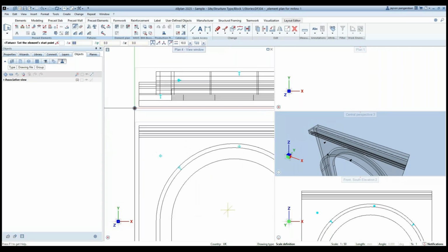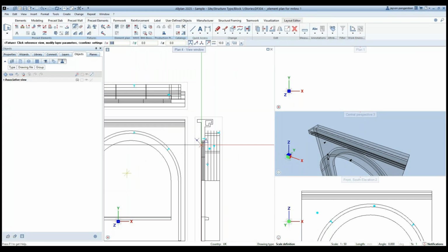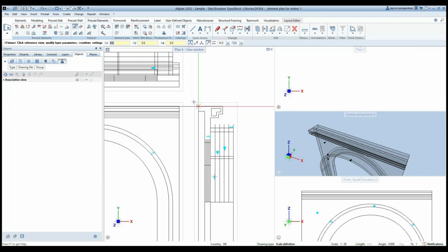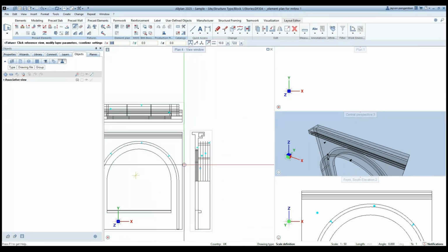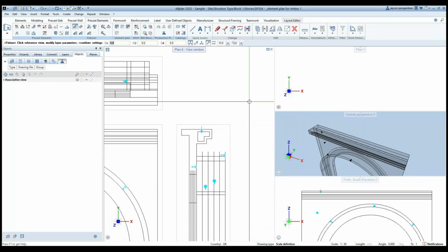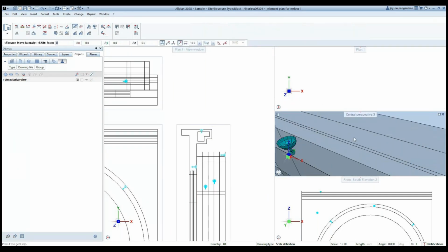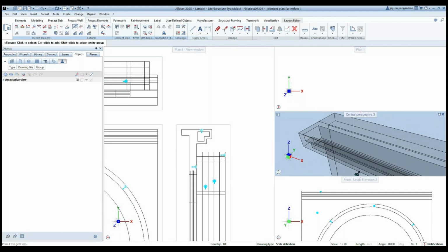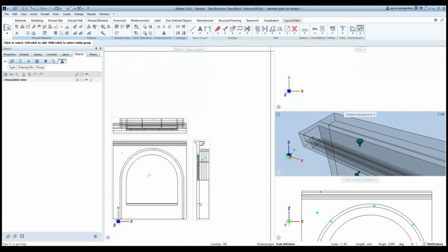So let's say at the top view, I have to go from here to here, and then I have to define in which level. So I have to pick the reference. You can see it goes up, and then you select OK. So it will stick on that area. So that's a big improvement when you place a fixture. And of course, when you place this fixture,